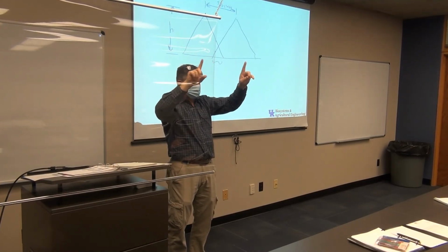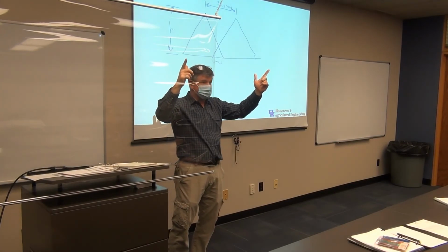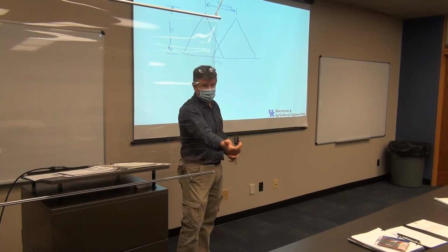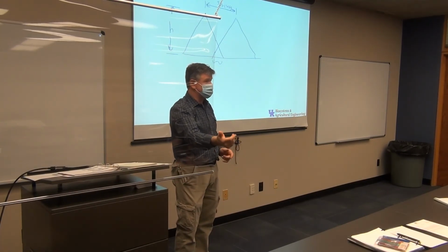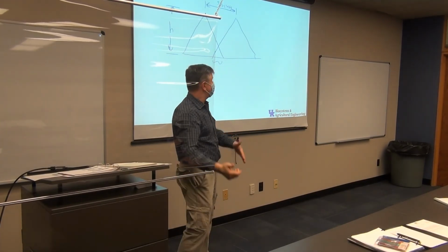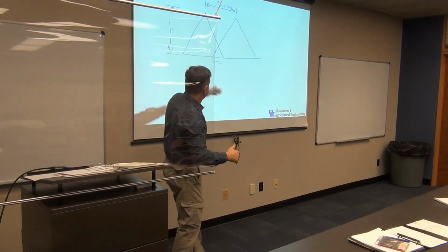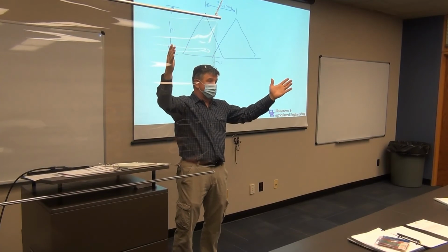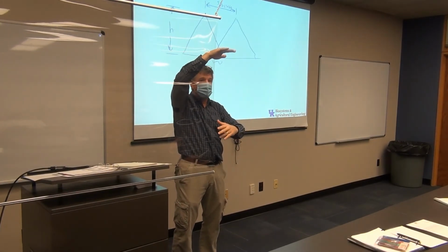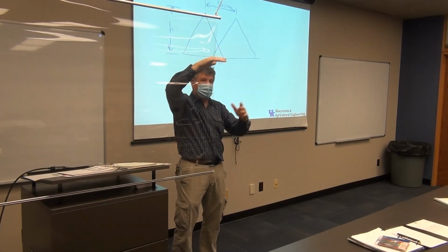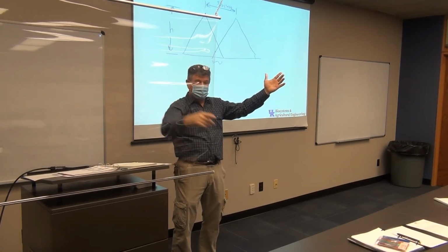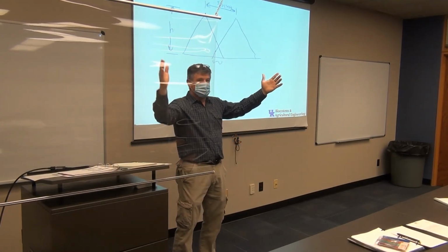All right? Now, in practicality, what happens most of the time is we don't change the nozzle spacing on there. So you're going to put the nozzles on, and whatever the spacing is on the boom, that's what you're dealing with. But now you ask yourself the other question, okay, we may have tested this at 30-inch boom height or something like that. And that came out with a spacing of 40 inches. That would be my optimum spacing. Well, these things are 20 inches. So what does that mean?